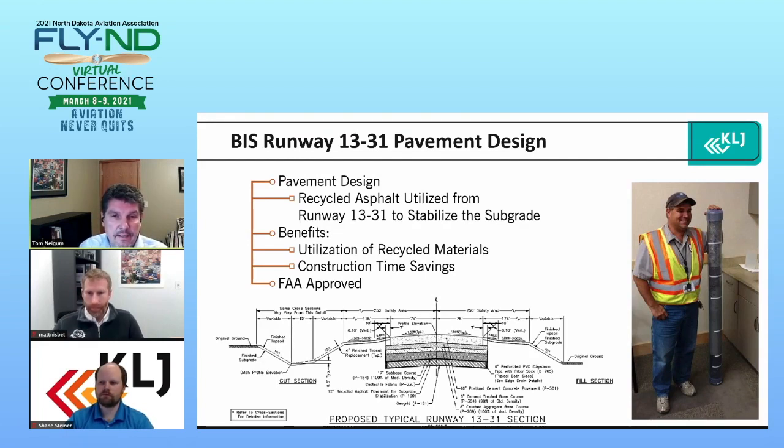And once we got to construction, just a side note, the contractor that did the first 2 phases of the runway, especially the first phase on the south end, said that if we didn't use the millings in the way we did to help stabilize it so they could more efficiently construct the runway, they would have been in trouble. He actually said they don't know if they would have been successful getting the first phase of the runway completed in the allotted time. So they were very, very happy that we had gone that route and sought the FAA approval to utilize the millings to start out as the foundation to build the runway upon.